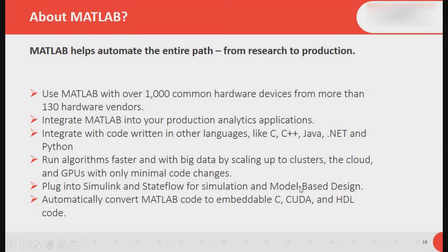All this process you can do in Simulink. Simulink is used for model based design, meaning you design your plants and controllers virtually there, then test and verify them. We have Simulink Test, Simulink Check, Simulink Coverage, Embedded Coder, C Coder, and HDL Coder for verification, like software in the loop or hardware in the loop.